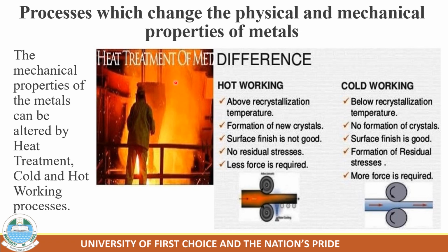That is the difference between annealing and hardening. During hardening, when you quench it urgently, all the microstructure gets stuck accidentally and the material becomes hardened. But when you heat it the other way, in order to soften it, the microstructure can easily settle down conveniently, and the material will be softened. That is the difference between hardening and annealing.